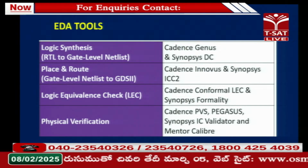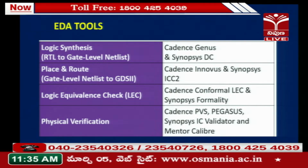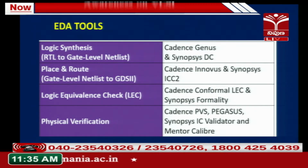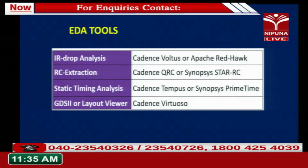These are the tools for the LEC. And for physical verification, DRC and LVS, Cadence PVS, Physical Verification System, or Pegasus, and in Synopsys we have IC Validator, and Mentor, I think now it is Siemens, Calibre tool for DRC LVS physical verification. For IR-drop analysis, Cadence Voltus, and one more famous tool is from the vendor Apache, RedHawk.